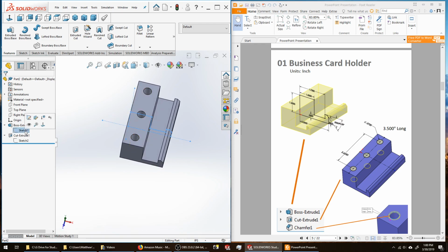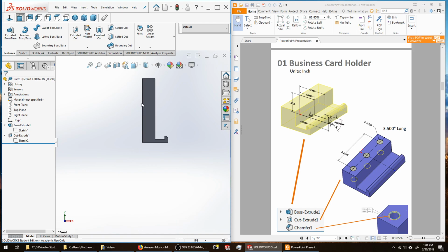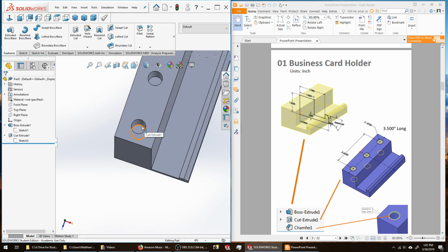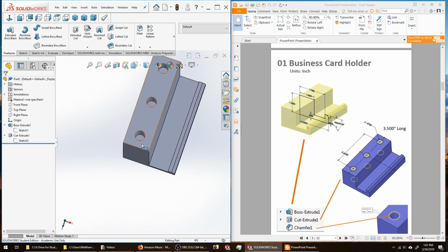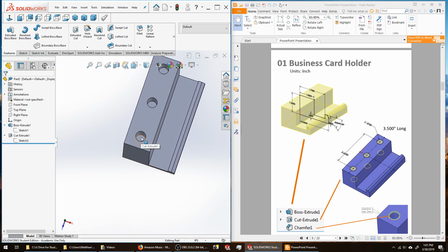Okay, so let's go back and change the height of the part again. I change this to 5 inches like I did before. Exit my sketch, say rebuild. Now the part does not have holes that go all the way through. The point there was that when I use blind and I give it a distance, if my part ever gets taller than the distance that I gave the depth of those holes to be, then the holes will no longer go through.